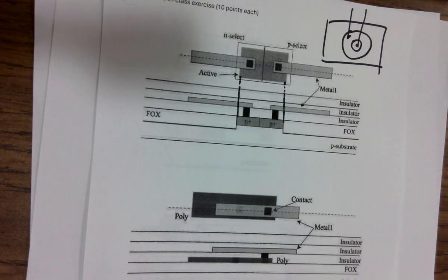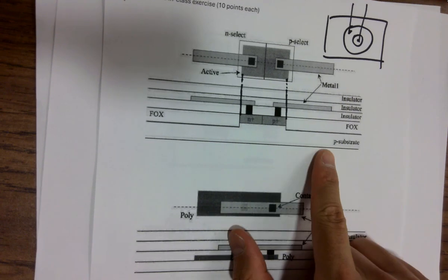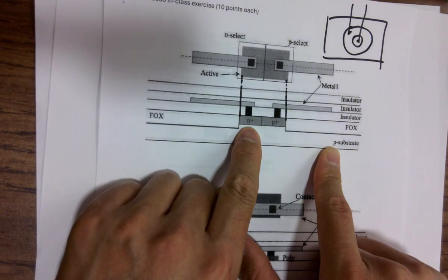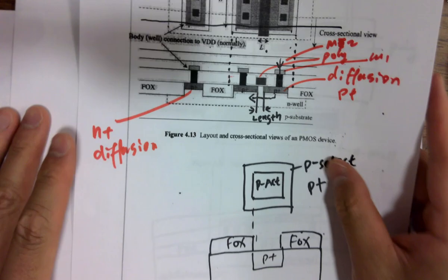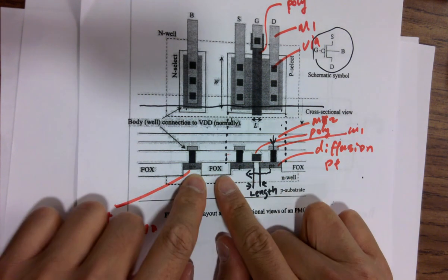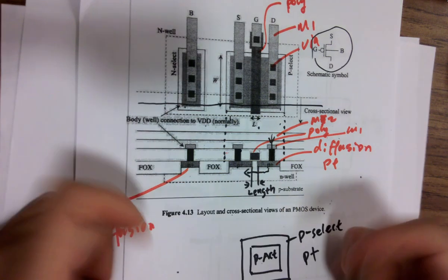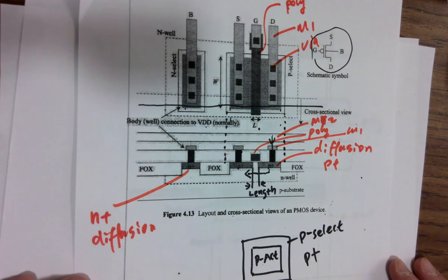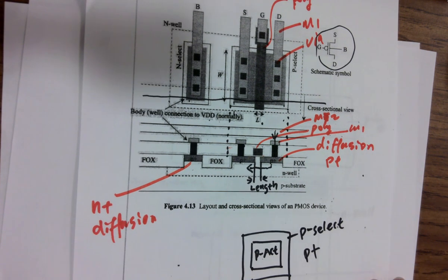So I think that's what happens, because you can see here, it's a P-type wafer. We can still dope it heavily with N plus concentration here to make it N plus, right? And same thing here for the N wells. I'm pretty sure that's what happens. So you can see the N well is N plus materials, N plus in the silicon, and we can make either P plus or N plus in it without any problems. Okay, I think that's doable. That's how that works, I think.